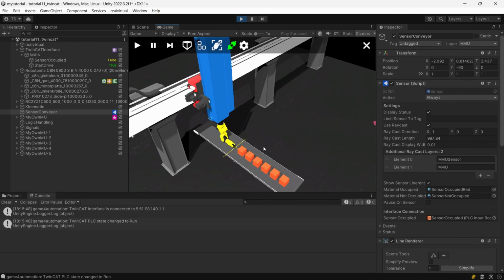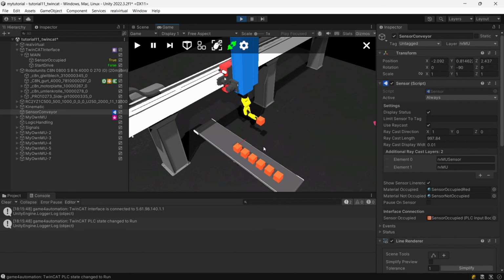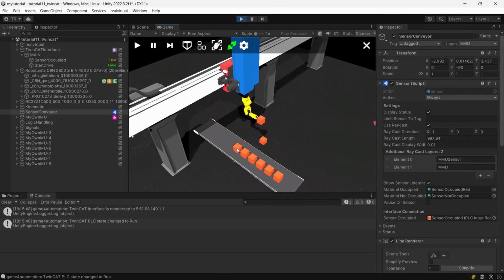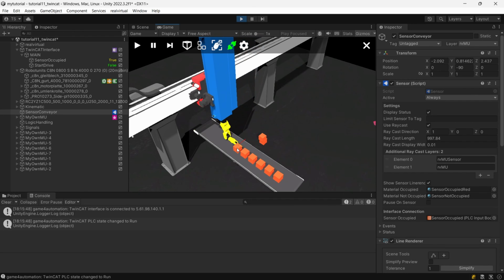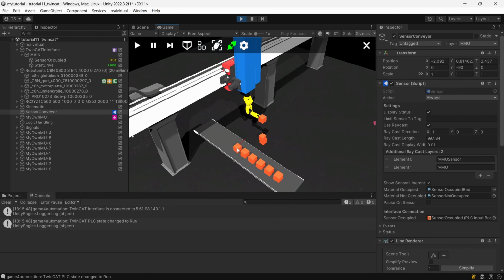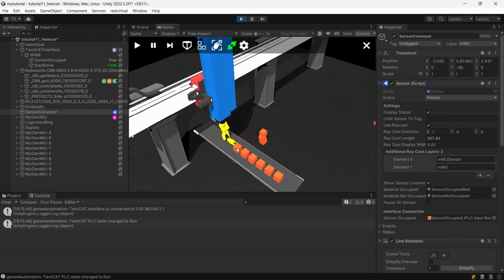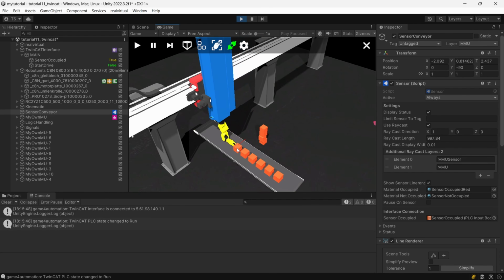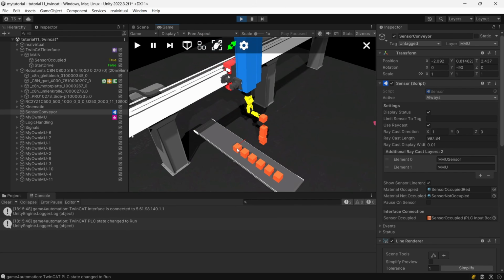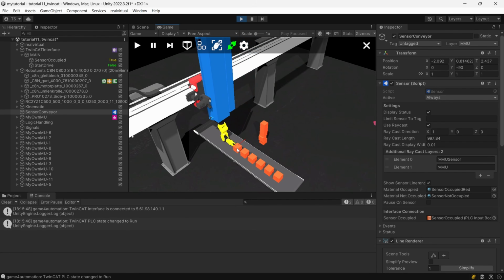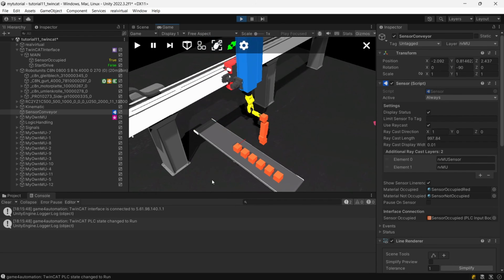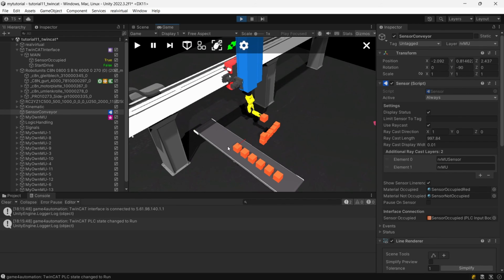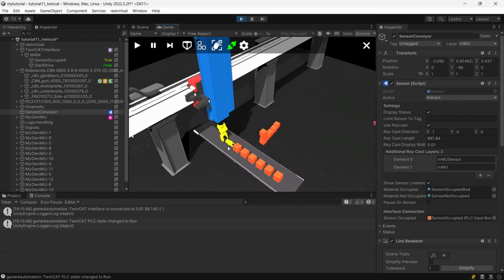But now it works as expected, because our signals from the inputs and outputs are not connected anymore to the PLC, because basically we deactivated inside the PLC this first terminal or module. So please always make sure to do that if you would like to do virtual commissioning and if real inputs and outputs are connected to the PLC.